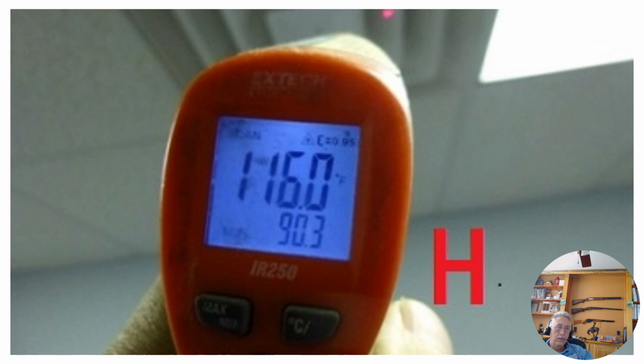Check for heat. Always use a laser thermometer. I check for actually working heat in every room, not just that there's a vent there. I make sure there's air coming out of it, or if it's a radiator, I make sure it's getting hot, and I document that way. I don't take a picture of every single vent, checking it with the laser thermometer, but I do check for it in every room. I just do 1 or 2 pictures like this to document that I tested it. So that's a good idea to do.